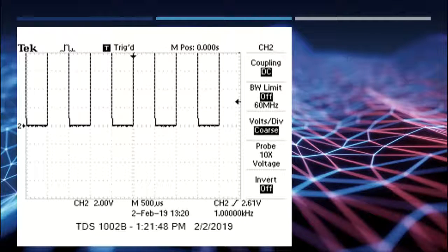Alright, so when I do that, here's what I get, a signal on the screen that looks sort of like this. This is our reference, it goes up, and it looks like part of the signal is actually off the screen. However, for the part of the signal that's on the screen, let's see how many volts per division. We have 1 division, 2 divisions, 3 divisions, 4 total divisions. And we also know that each division is represented by 2 volts, as shown here.